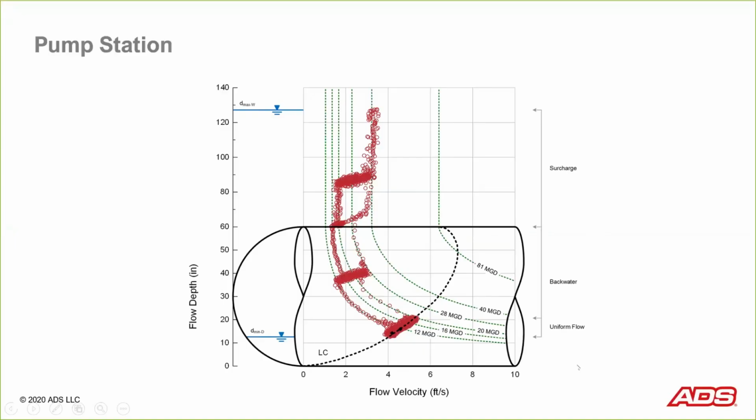But this is some very interesting data here and shows you the complexity of the hydraulics upstream from a station like this. But with a little bit of extra information from the municipality or the consulting engineer that you might be working with, along with your scattergraph tools like the Manning equation and some ISO-Q lines, you can learn some interesting things either about how the station is performing, or the people that are controlling the station can learn some interesting things about how the station itself is impacting the upstream line. So very interesting case there.